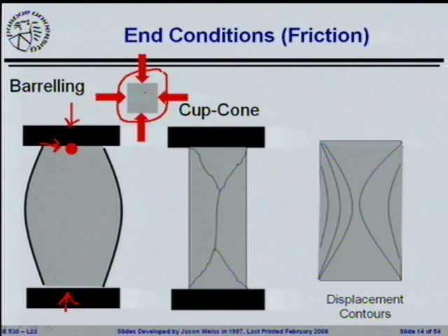Now, when you get a geo material that has confinement, you completely change the behavior of that material. You think about it with sand. You step on a pile of sand, the sand sinks. You take that exact same sand, you put it in a bucket, you apply some confinement, there's a lot more resistance of that sand. Here, you're providing confinement at the end of the samples.